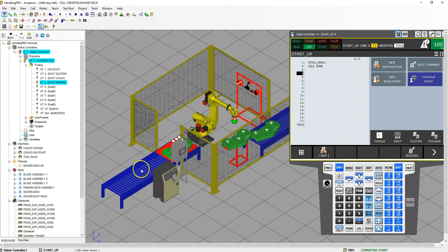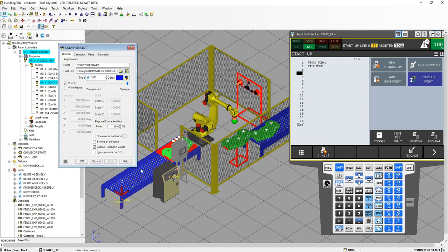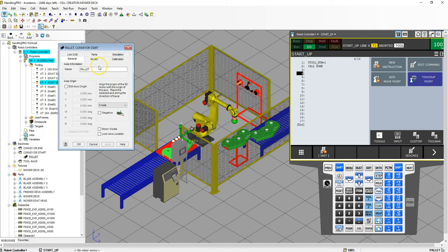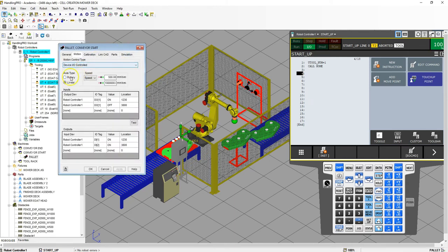If you don't remember which digital items that is, you could just easily double click and then you will see the different parts. But what we need to actually double click is the machine part. So double click the machine part, which is our pallet. Here's our motion. So digital 1, when it is on, it's at its starting point. So we can just easily check, just go here and test. There's our starting point. Okay, and then we can also wait until digital 1 is on as well.